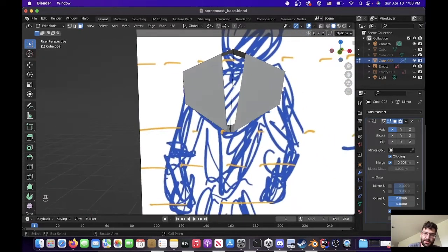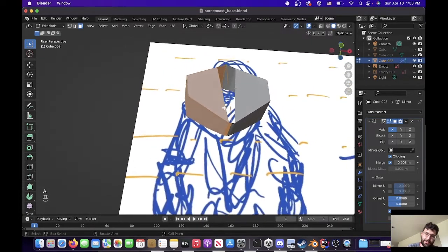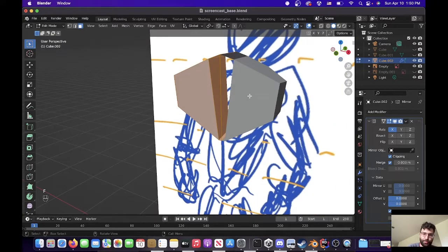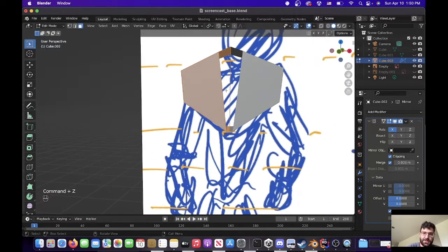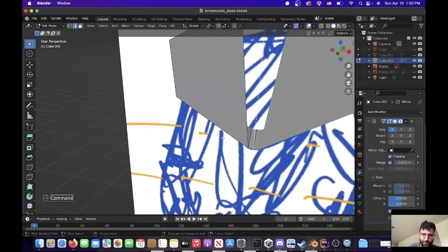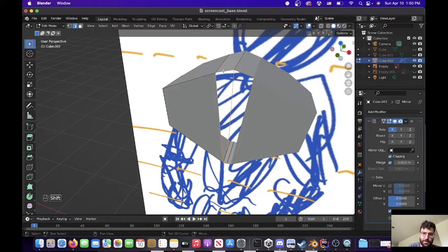And now we're actually gonna, here's a fun trick. If you hit A to select all of the detail in your model and you hit F again, nope. Sometimes that works, sometimes it doesn't. Now we're gonna do that thing with loops. So geometry modeling is all about loops. Can I get that? Yep, I can get that. When you have four-sided loops, you're in good company because you can turn those loops into faces like that.